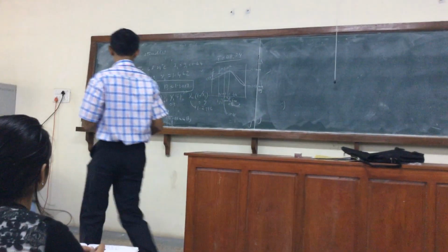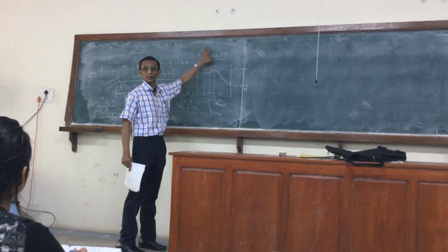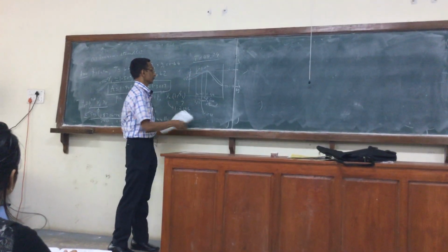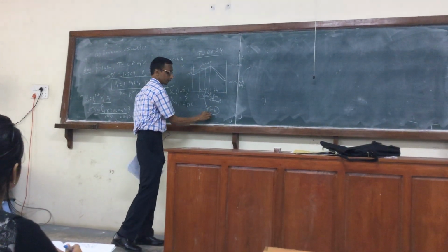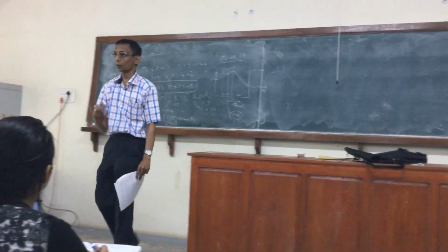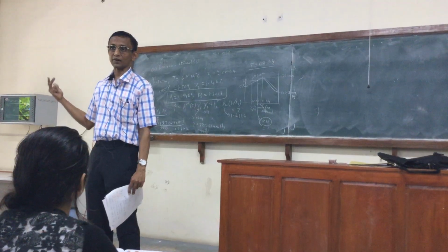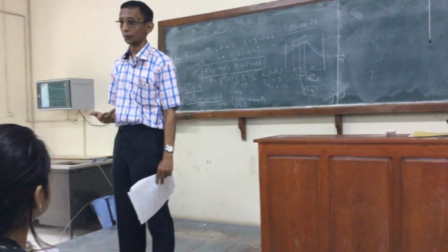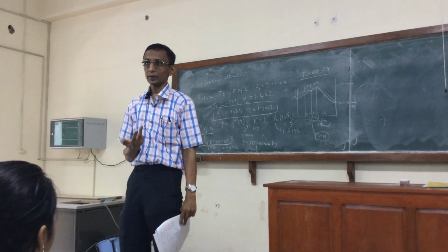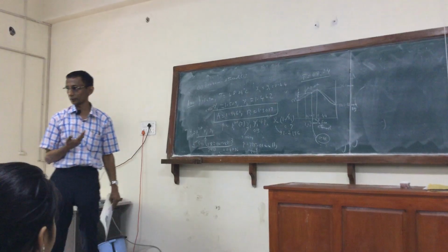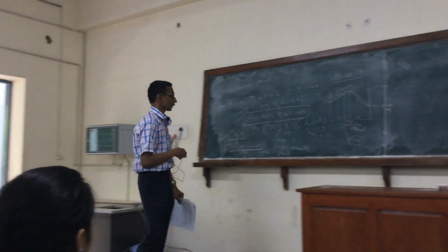The only thing is that we are not fixing the y. Whatever y we get, we take that, and I can easily construct the P versus y curve also. So this gives a point on the P versus y curve. Same pressure, what is the y? Rather than solving the dew pressure problem for various values of y, where in each stage you would require an iterative calculation, that would be really not a smart thing to do, right? So that you have to understand. So I can consider that.